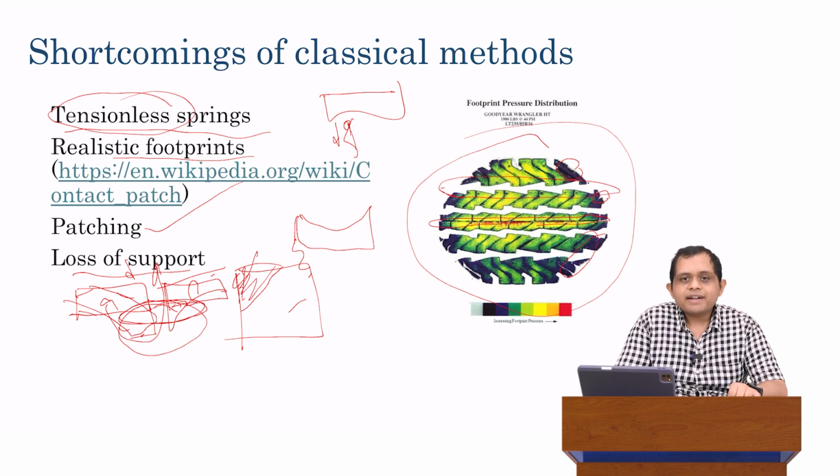When you have a void just below the joint, you basically do not have anything to support the slab at that point. Just in that small area near the joint, we say that the slab has lost support. Now, that can have some very serious implications on stress. It is very important that we critically analyze and identify these situations. Unfortunately, the classical methods can't do it at all.